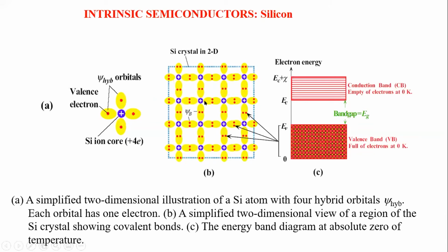So a silicon in this case, if you see here, will have an electron shared with the neighbor across all the directions. If they start to share the charge density, or in terms of quantum, we say overlap of wave functions, then we say that the bonding starts to be established.